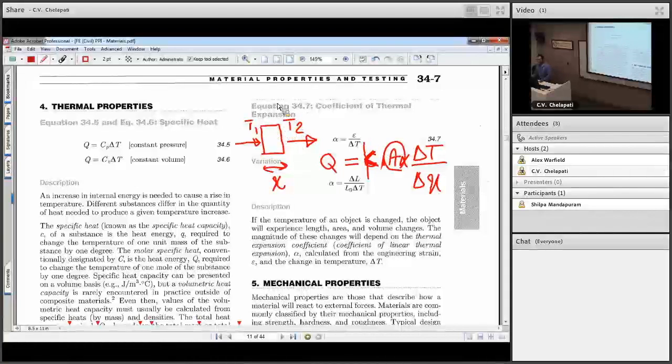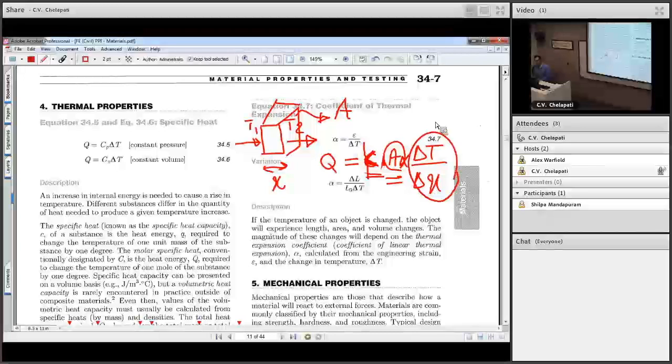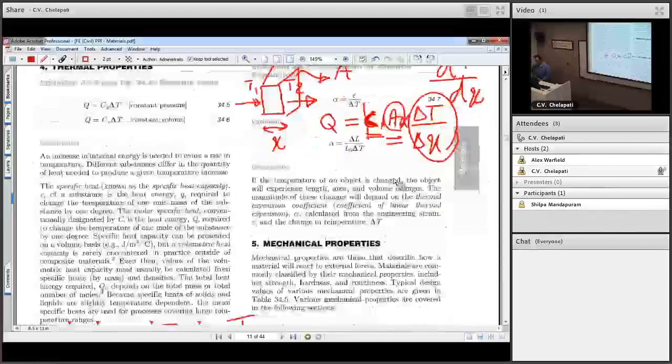And the next part is the thermal property, thermal capacity of materials. So this is the equation for it. Q equals m c delta T, the amount of heat flux that goes into the material to change the temperature by delta T. That is equal to M, the mass, multiplied by the thermal capacity, multiplied by the change of temperature. And that's the equation that you will use if you see any equations of this sort about thermal capacity.